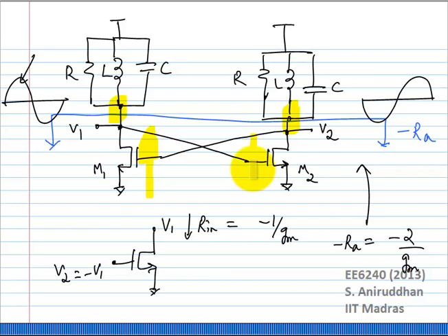Okay, but in any real oscillator, what do you think will happen? Let us say I'm actually designing this oscillator, taping it out, and I have it on an IC. How do you actually get it to oscillate? There are actually many different ways, right? For example, even turning on the supply of this oscillator could give you enough of a jerk and enough of a difference between the two nodes to actually get the circuit oscillating.